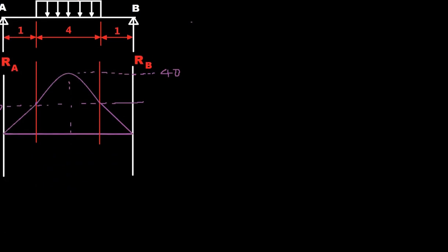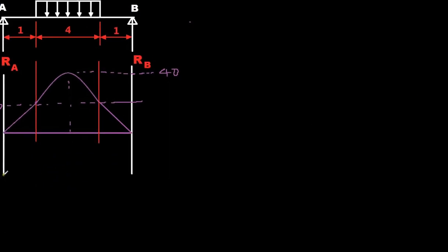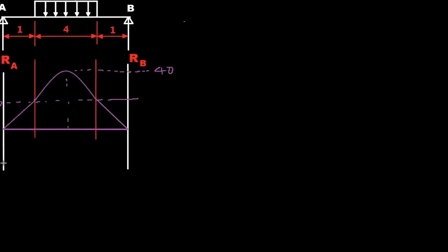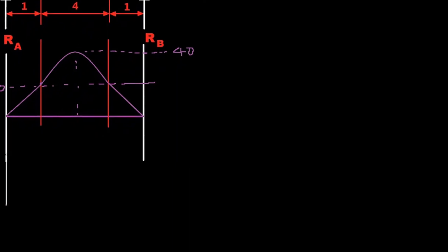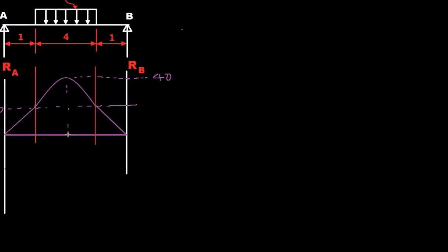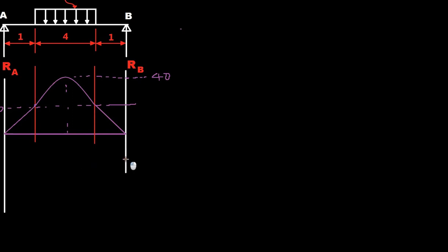And from this you can also draw the shear force diagram of this force system. That again is pretty simple. Once you have the bending moment, it's easy to draw the shear force diagram. So if you have the bending moment diagram, you can just use that to generate your shear force diagram.